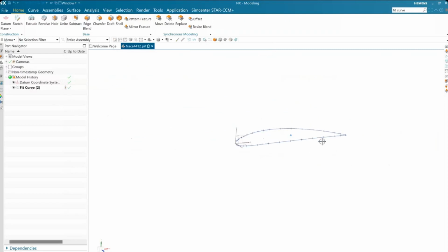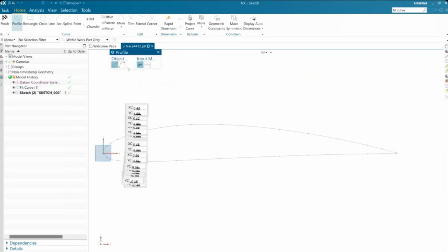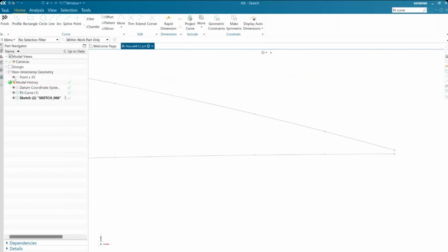Now to finally cap this off, if you can't extrude this, you're going to want to go to Sketch, Simple Sketch, Advanced Settings, of course, and then, because you're very proper, you're going to want to go to Project Curve, and project these 2 points, and you want to hide the points because you like that.